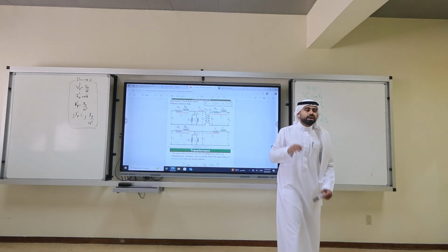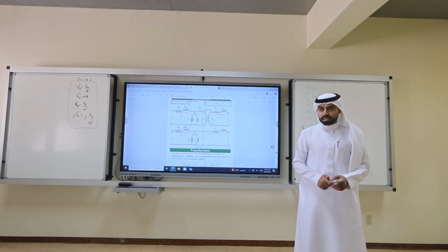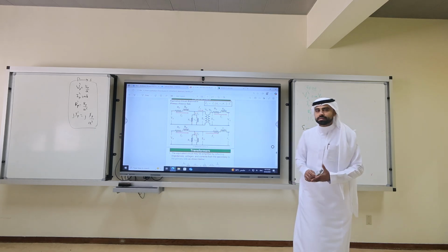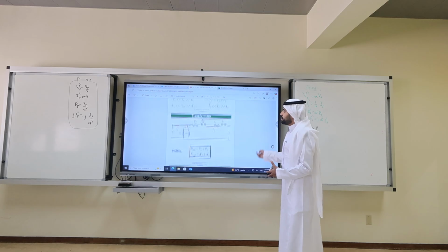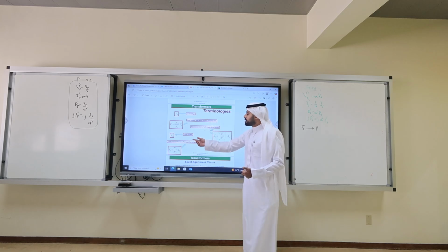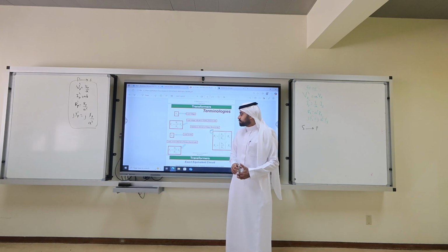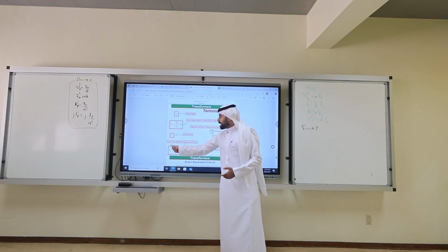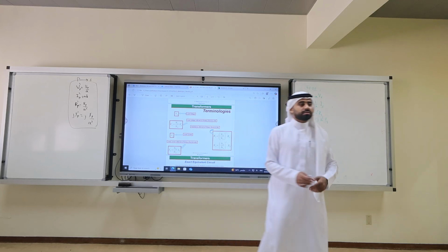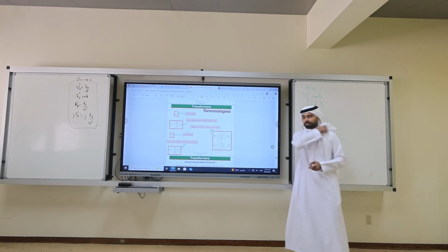In some books, they don't tell you reflected to the secondary and the primary, they tell you the load reflected to the source. Get it? The load is the secondary and the source is the primary. So that is the purpose of the terminology slide. It's not only that. IS, is it the load current or the load current reflected? Load current. IS prime is the load current reflected. I don't like to use the word reflected. Just use referred. It's better. Referred has more meanings than reflected.